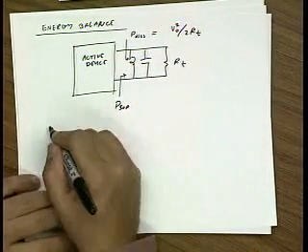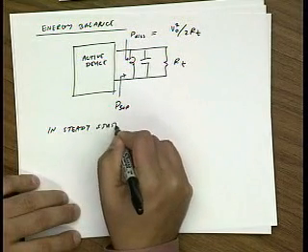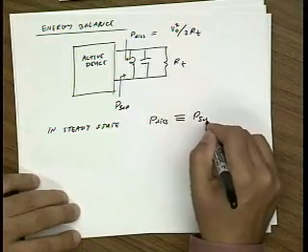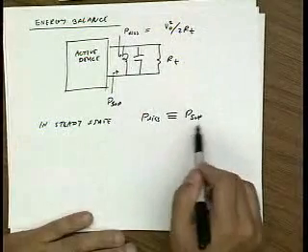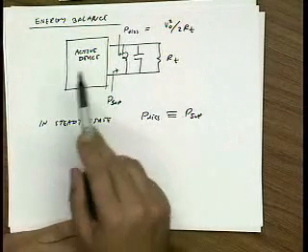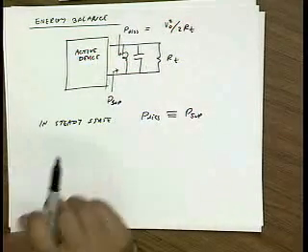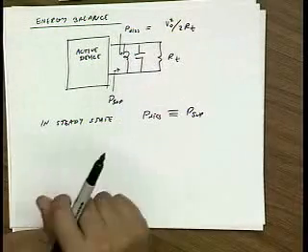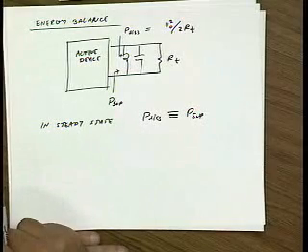So in steady state, the power dissipated has to identically equal the power supplied. So this is the average power dissipated, this is the average power supplied. Now the power that the active device actually supplies can be bursty. It can basically supply bursts of energy into the tank, but on average, that energy has to average out to the power that's being dissipated in the tank, right?